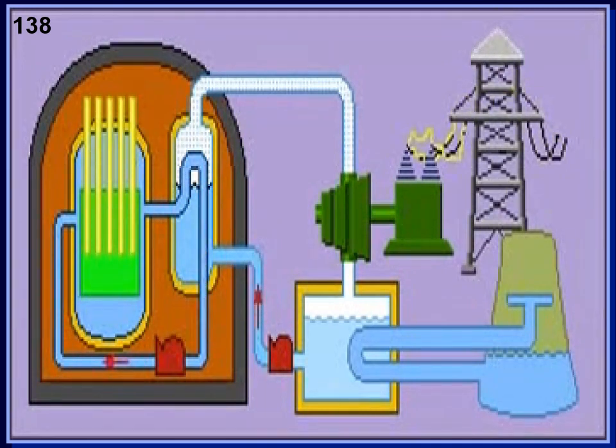Heat from loop 1 boils the water in the steam generator, and the energy from the steam powers turbines that drive electricity generators. The steam is then cooled and condensed in a heat exchange with a third water loop, which carries water from the cooling tower. The liquid water in loop 2 then returns to the steam generator where it is reheated and the cycle continues.